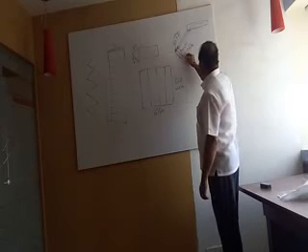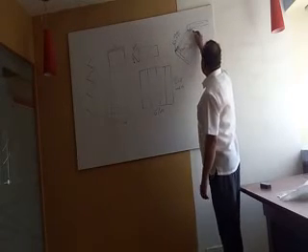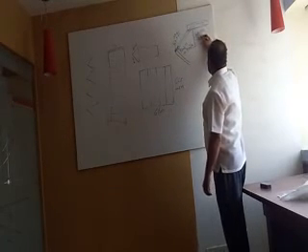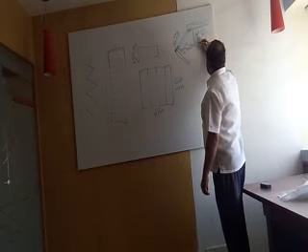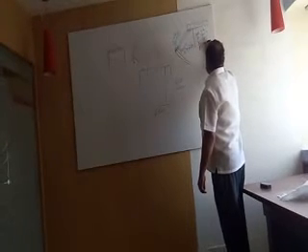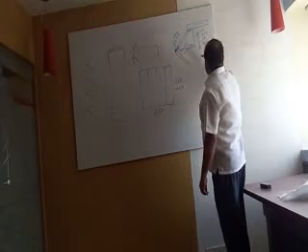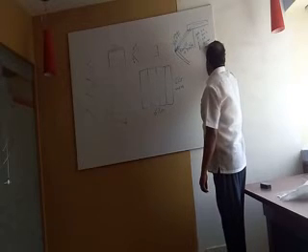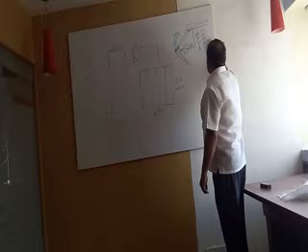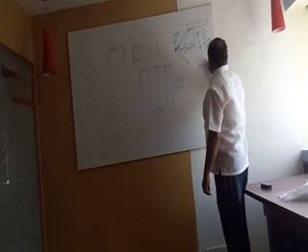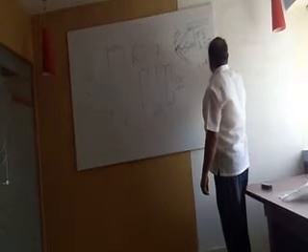So what is this? The head is 3 meters. Discharge is 9,000 liters per second. Gravity is 9.81. Efficiency, that is mu, is 94% max. In this way we will be generating 158 kilowatts of energy per sector, because head into flow into gravity into efficiency is the formula for power generation.